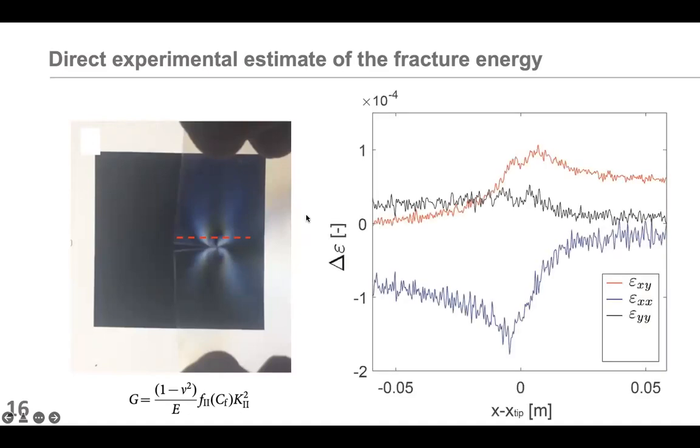So if I plot the stress intensity factor, the stress singularity at the rupture tip during one event, I can plot it as a function of distance from the crack tip, if I consider a constant rupture speed during each event. Knowing that experimental data, it's possible to model them, knowing the position of the strain gauges along the interface and knowing the rupture speed.